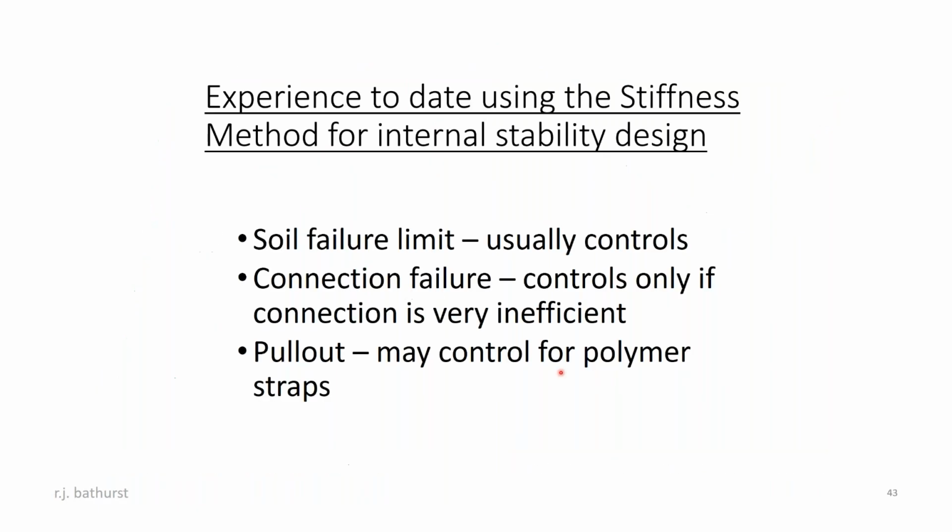Our experience to date with the stiffness method is that the soil failure limit state usually controls. The requirement to keep the strains in the reinforcement to low critical values is most important, so that the soil is at a working stress condition. Connection failures may happen if the connection is very poor, but to be fair, the manufacturers of these systems have developed connections that are quite efficient, so